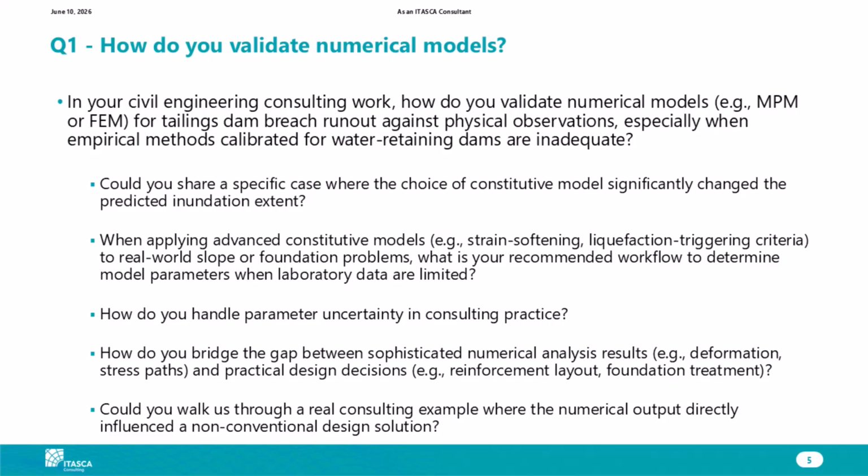And you can do that even with closed-form solutions, of course, right? You can take a Brinch-Hansen formula, plug in a friction angle, and come up with different types of bearing capacity, for example, or a settlement analysis and whatnot. But the advantage of numerical modeling is that it captures much better the physics and the mechanics of the whole system. This is more important when you have a complex system.